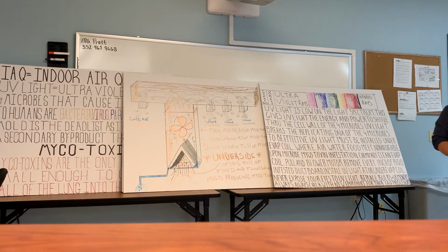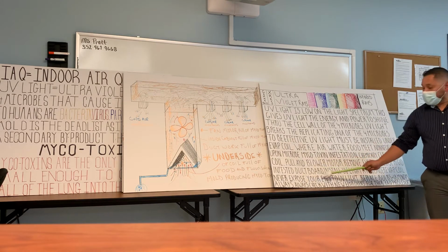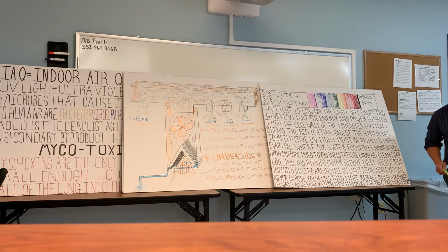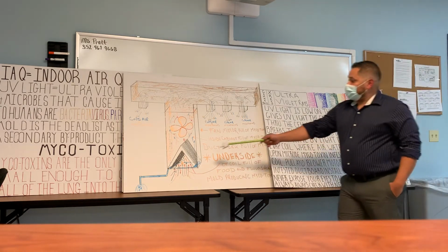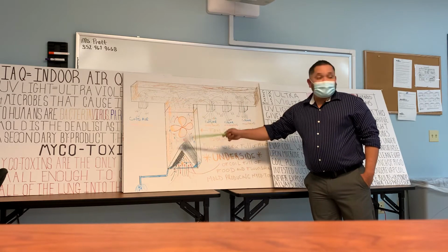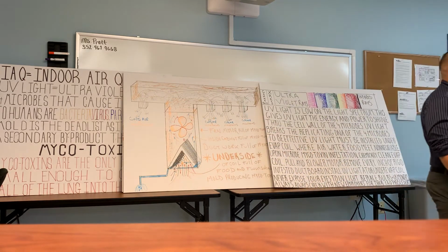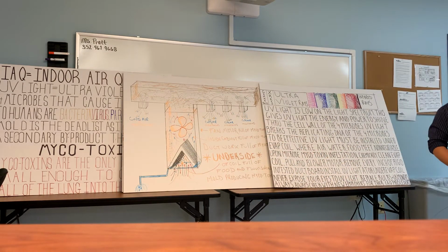I don't want to send you out there in the field knowing why and how. You need practicality. First off, never expose your eyes to UV light. Never. It's very tempting. You install it here, the panels are off, you turned it on, the light's shining out. This light will cause temporary blindness. It's not instant. Happened to me in 2005. Had the panel off, doing some zip ties. The light was on. I didn't realize it. My exposure time was maybe 90 seconds.